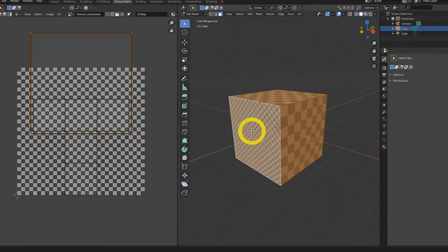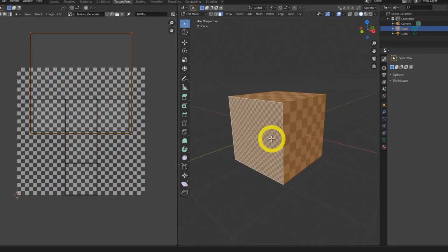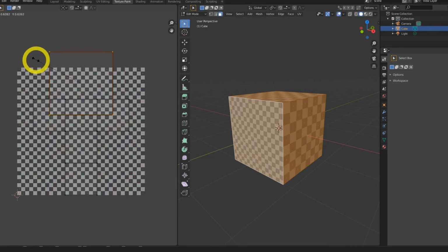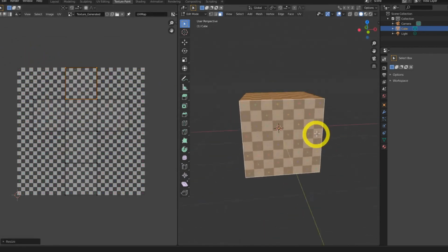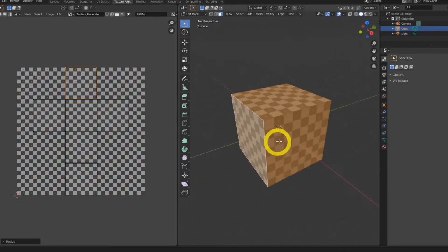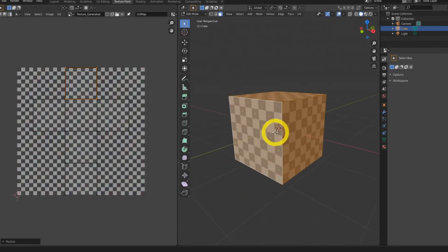Another way we can use this is the other way around. When you already have unwrapped something or auto unwrapped something, sometimes the pixel density is then too high. Then you can go to the UV editor, select that face and scale it down until the pixel density is the same as the other parts of the model. Now all the faces on the model have the same pixel density again. So that's what the generated types are for, to be able to see the pixel density of every part of your model. And then there's the other texture, the other generated type.